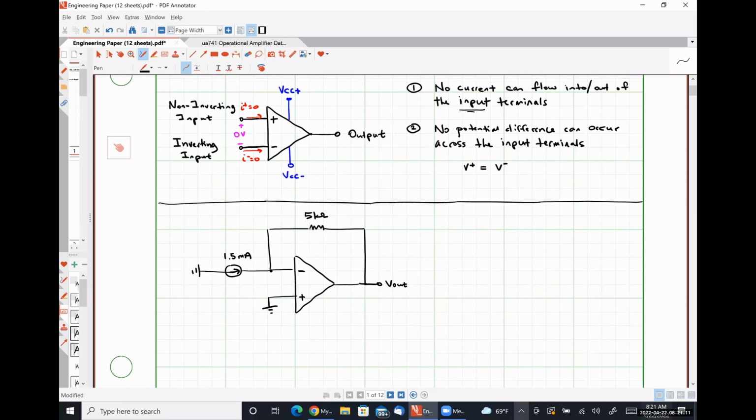That could be a resistor, a wire, a capacitor, an inductor, a voltage source, etc. But whenever there is anything that isn't an open circuit that links the inverting input terminal to the output terminal, we have negative feedback, and we can use those two rules that we described above. As I mentioned previously, every circuit in this class that has an op-amp is going to be that type, but I just wanted to explain what I mean by the concept of negative feedback.